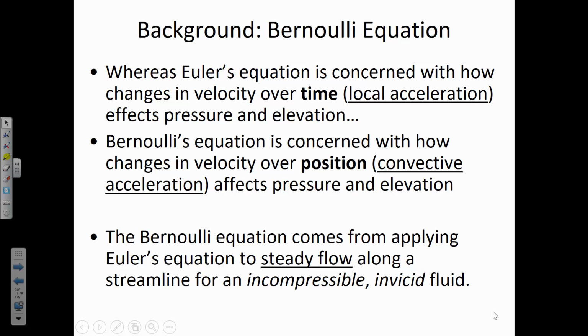The next limitation is that we're assuming it's an incompressible fluid. Now, water is relatively incompressible. It's a little bit compressible. Remember when we talked about bulk modulus for water? If we apply many gigapascals, we can get it to change a few percent in volume. But for the most part, water is a pretty ideal fluid to apply Bernoulli's equation to because it is incompressible.